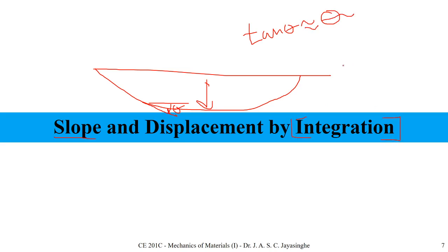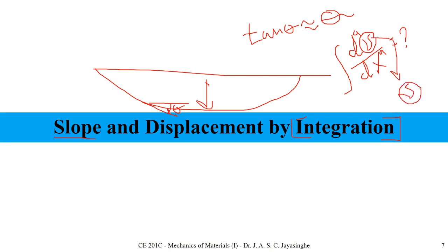We are going to derive the deflection equation in terms of dx with some power, I don't know which power we end up with. After that, to take this deflection equation, you need to do integration with respect to these values. By integration you can end up with the solution for deflection and at the same time rotation.